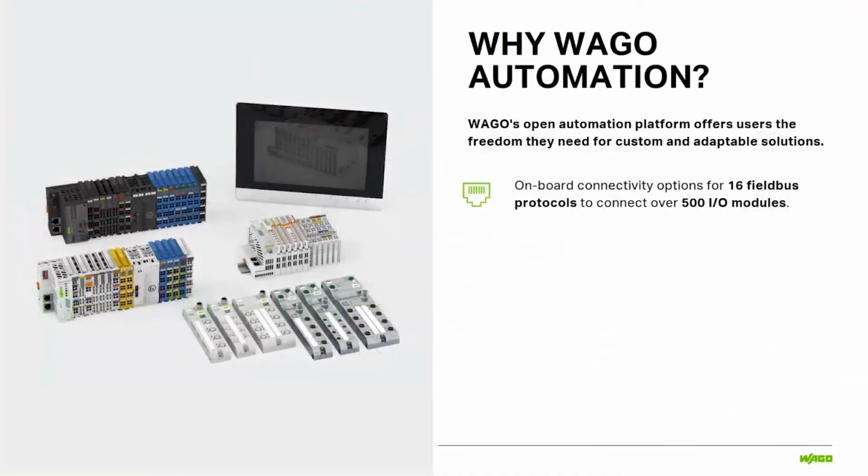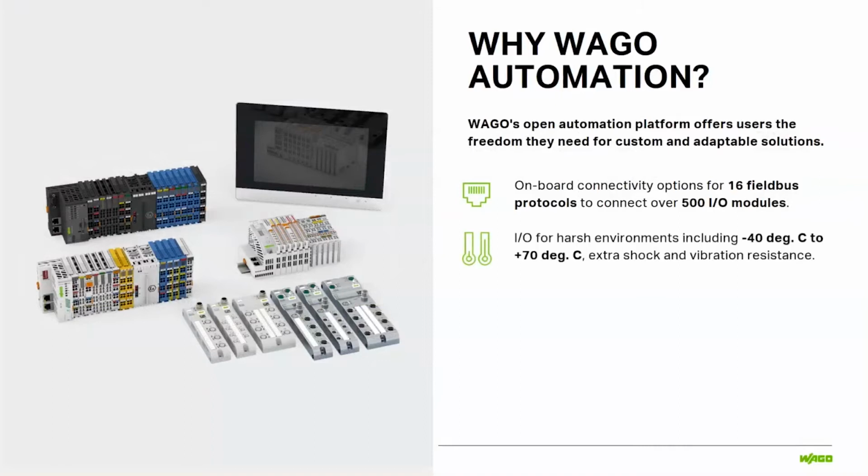So if you were asking me why some of our customers use WAGO, especially the automation side of things, one of the reasons is because we actually have onboard connectivity options for more than 16 different industrial fieldbus protocols. So we can even have multiple fieldbus protocols on one PLC, which is somewhat unique because you can kind of use it as a gateway in that way. We've got IO for harsh environments, including plus 40 to plus 70 degrees Celsius, extra shock and vibration ratings.